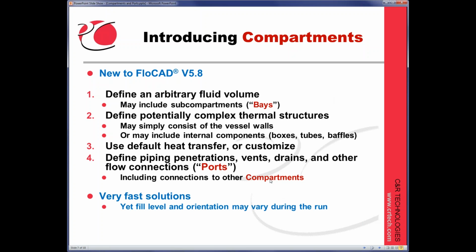Here's the key of the compartments. We talked about this is more than what you're used to seeing in a flow network or 1D thermal-hydraulic network modeling system. It's a lot less than what you'll still see in a CFD code, of course, because the entire purpose of compartments is to run very, very fast. The orientation, the fill level may vary during a run. The fluid can move around, but it's still not CFD.